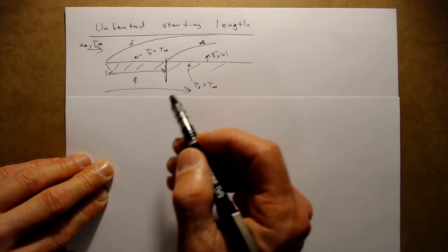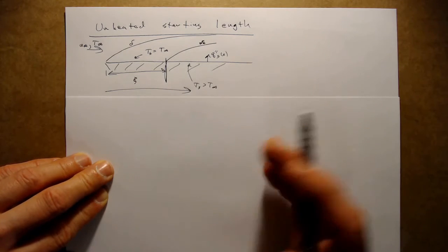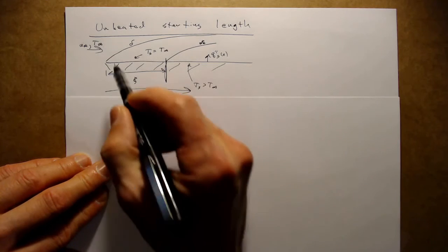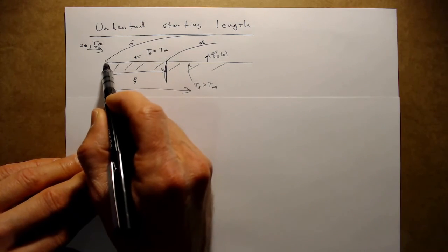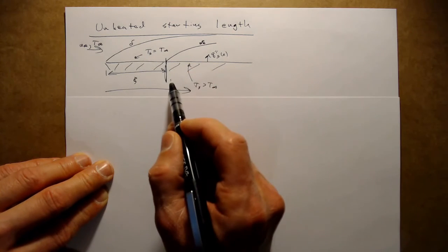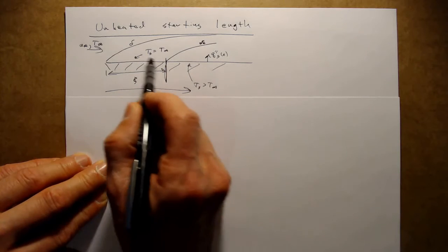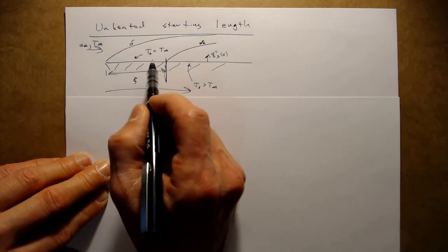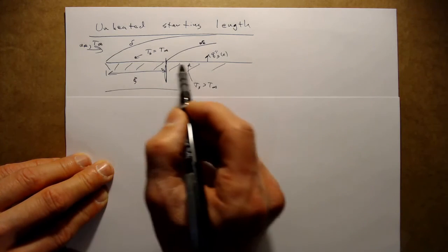So now the two boundary layers develop differently than each other, or at least they start developing at different locations. The velocity boundary layer is developing as soon as the flow hits the leading edge. So the velocity boundary layer is growing, but there is no thermal boundary layer in this leading region, because it's unheated and the temperature of the plate will just be at the temperature of the free stream.